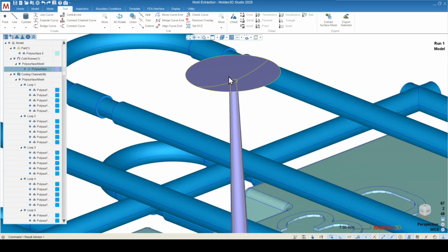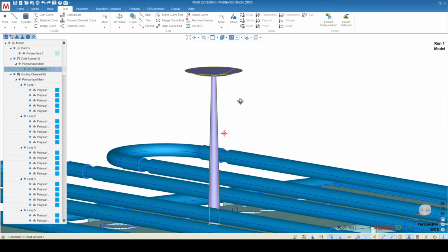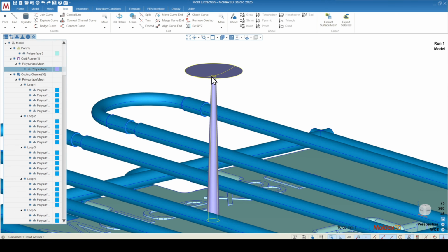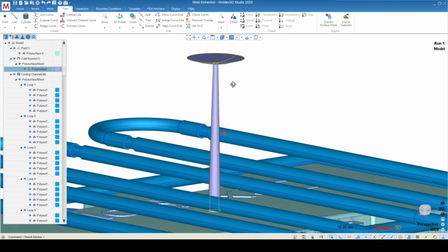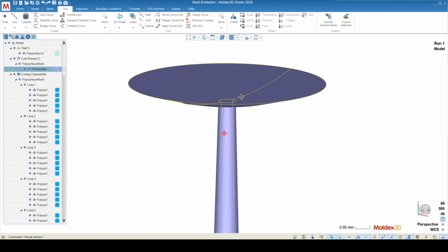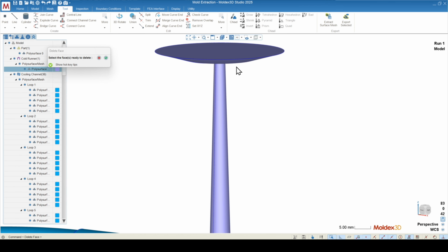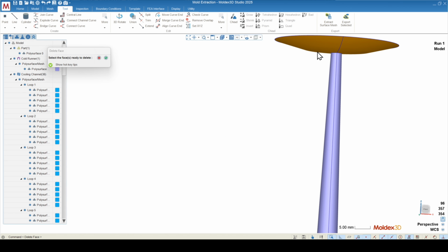Now, I mentioned earlier that the interface with the nozzle was also extracted, which isn't always the case, but maybe the coincident angle here was a little bit lower than 90 degrees, so it might have automatically associated that. But let's go ahead and remove these unnecessary surfaces. We can do that under the Edit Tools, More, Delete Face, and I can just select my object and then find those surfaces to delete them.